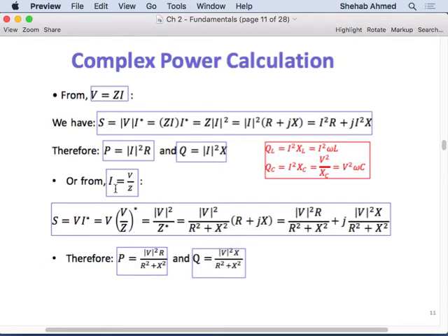And just rewrite Ohm's law again: instead of writing V equals impedance times I, you just solve for I and substitute. Instead of solving for V up here, we solve for I down here and rewrite the apparent power equation in terms of voltages and impedances instead of currents and impedances, right? So sometimes you're given this, sometimes you're given that, and it's really nothing more than direct substitution, right? So, any questions on these equations? It's Ohm's law with simple direct substitutions into the apparent power equation. Okay?